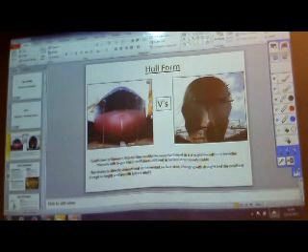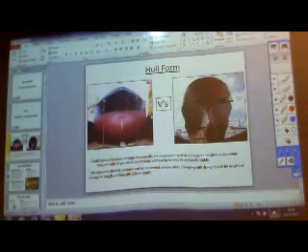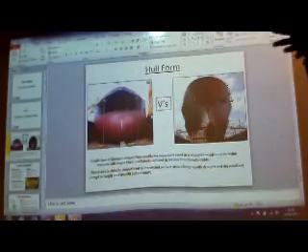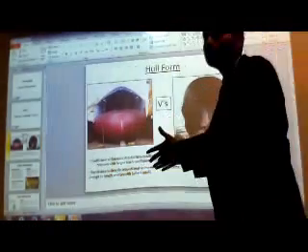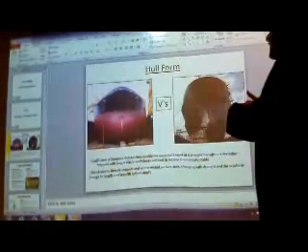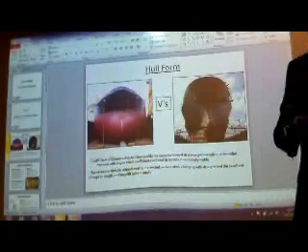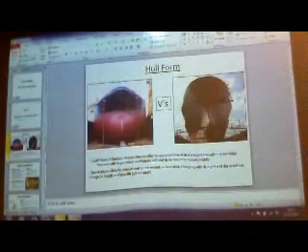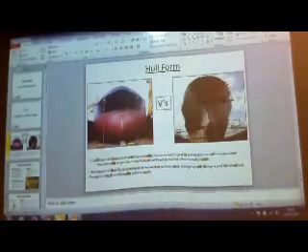This is what we were discussing. Yes, hull form will initially decide upon some of the factors that you can control right from the design stage. But this factor will then be based on the needs of where the vessel is going to operate, area of operation, volume that you want to carry. It is a variable factor. Every ship cannot be designed in the same way.